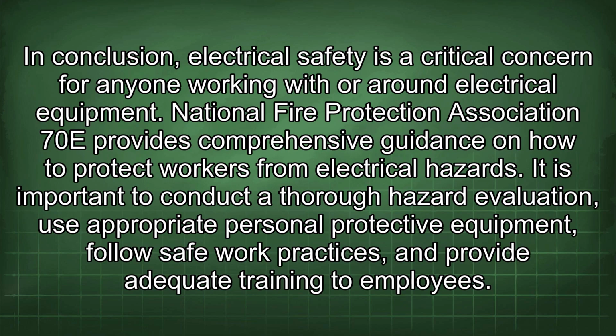In conclusion, electrical safety is a critical concern for anyone working with or around electrical equipment. National Fire Protection Association 70E provides comprehensive guidance on how to protect workers from electrical hazards. It is important to conduct a thorough hazard evaluation, use appropriate personal protective equipment, follow safe work practices, and provide adequate training to employees.